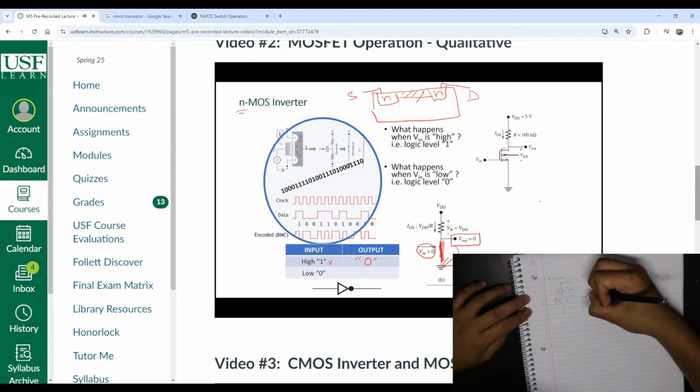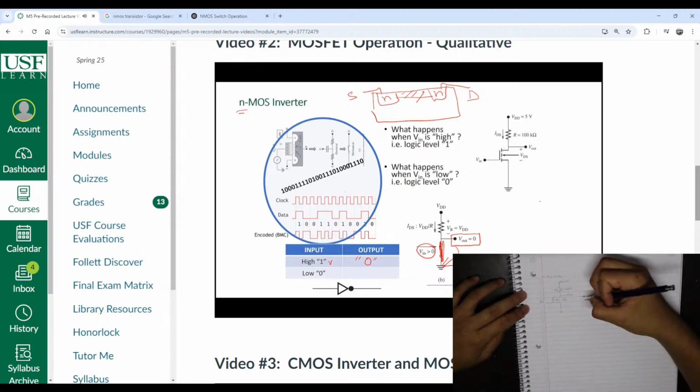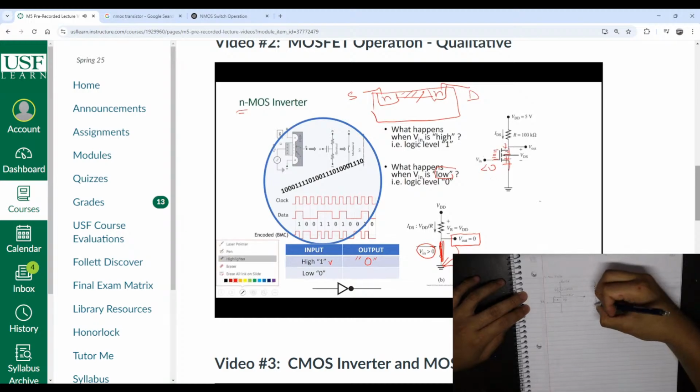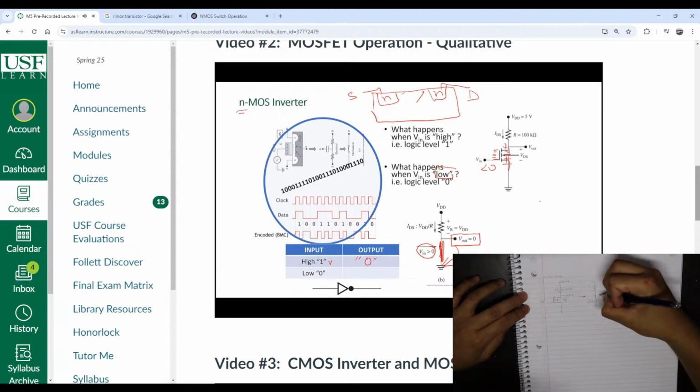Now we're going to take a look at this same NMOS transistor under the condition that we put on a low voltage or a negative Vin, right? Less than 0. If we put a negative Vin on the gate, that means we're going to put negative charges on the metal here, which means we're going to put positive charges in here. If I put positive charges right here, my p-type region that was there originally is not going to change.